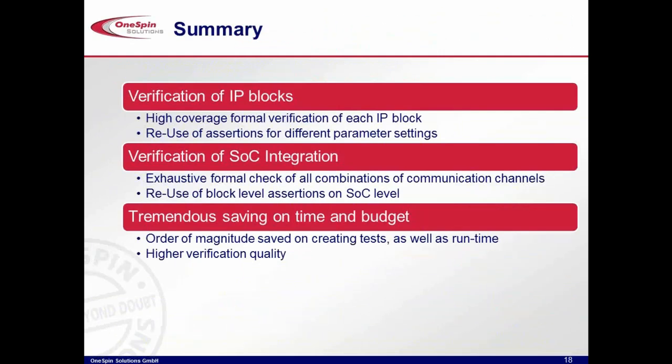So in summary, we saw a little bit of verification of the IP blocks, these kinds of transaction-level assertions. And we saw how these assertions that are shipped along with the IP could be leveraged for SoC integration verification, and provide higher quality and also savings in runtime and human time of almost an order of magnitude.